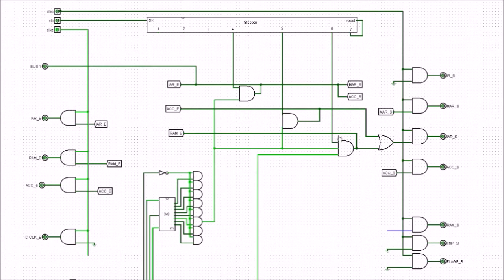That's in effect the choice being made at that point. Does the instruction address register contain the address for the next instruction from the accumulator, or does it contain the value from the next place within the RAM? That's a choice that's been made, and whenever this 0 goes high, it's going to come from the RAM. So the next address within the RAM will contain the place that you actually want to jump to.